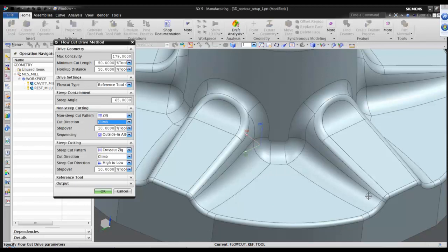That's a really good way to do things, because if this was not doing it that way, you could have a chance that the cutter would be coming straight into here and taking a pretty heavy cut right in the middle of that corner. So it's always a good idea to work your way from the outside to the end of a corner when you're roughing out larger amounts of material.